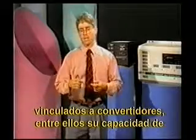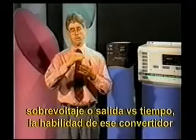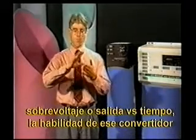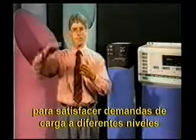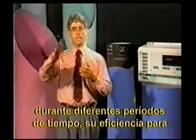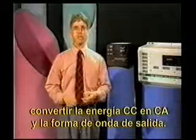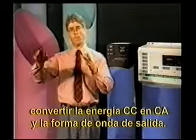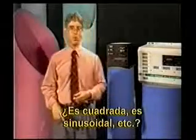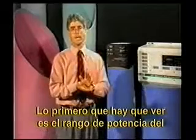inverters. Some of the main factors that come to mind are the surge capability of the inverter, or the output versus time, the ability of that inverter to meet load demands at different levels for different amounts of time, the efficiency of that inverter in terms of converting DC energy into AC energy, and the output waveform. Is it a squarish type of form? Is it a sinusoidal type of form? And so on. First thing we want to look at is the power rating of the inverter.